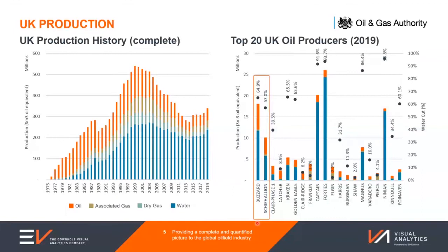So in these two scenarios where you have high oil production and relatively low water by comparison, you're probably looking to find significant changes in water over time and act on a well-to-well, case-by-case basis. And you probably won't act until the impact is significant enough that maybe you're losing primary pressure drive and you're having to think about artificial lift. So perhaps then you could look at going in and eliminating water at source.